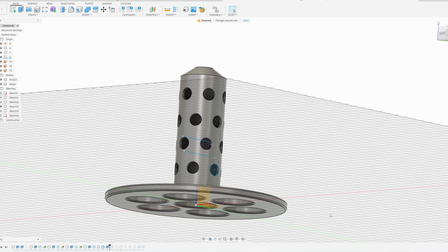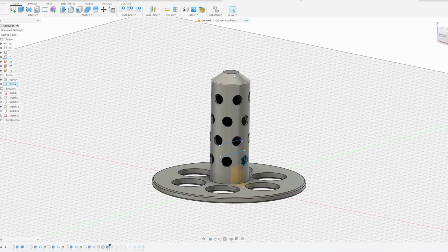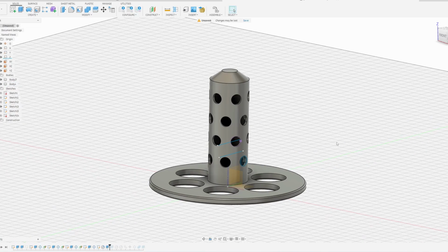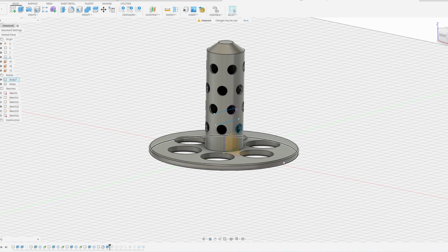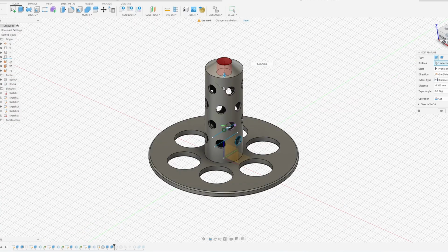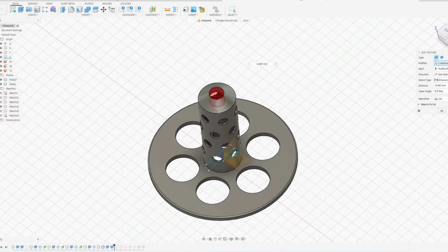Here I'm making sure that I completely finish this pipe, because I'm going to copy it. I'm going to finish doing some fillet around these edges, and then it will be ready to copy. So basically I finish it by creating a hole in there. As you can see, if I click on it, I made this hole in here, and okay.